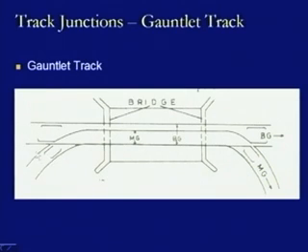So, what we are doing here is we are merging the meter gauge with the broad gauge. So, this meter gauge line will come and will join this broad gauge line at this location. So, we have to provide a connectivity at this location, where what we found is that this becomes a crossing. So, we have the wing rails located here along with the check rails, and because the size of the meter gauge is lower than the broad gauge, this line will remain extra line other than this one.